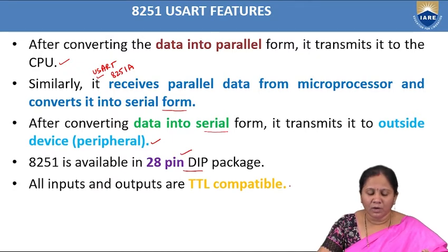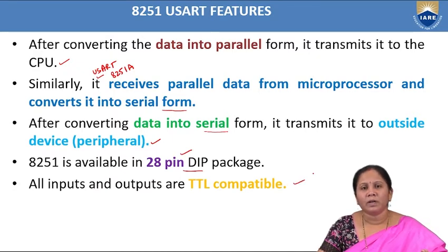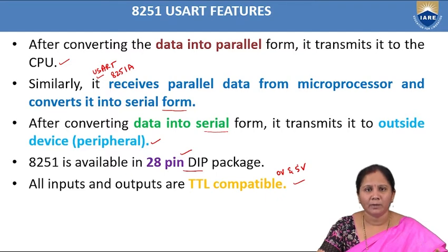All the inputs and outputs are TTL compatible. TTL means transistor-transistor logic, where the voltage levels are represented as 0 volts and 5 volts. Generally the data will be transmitted in the form of binary, either 0 or 1.